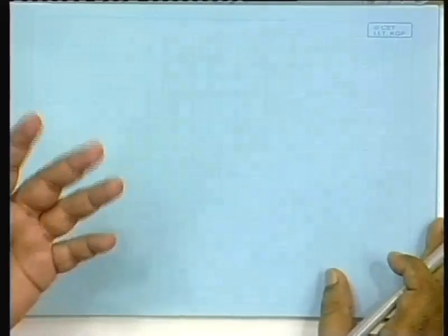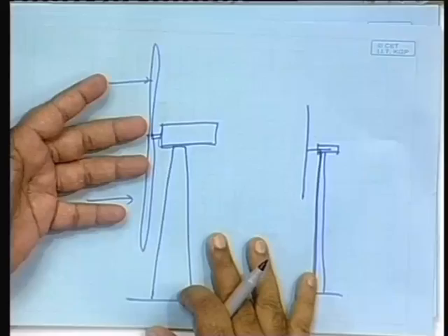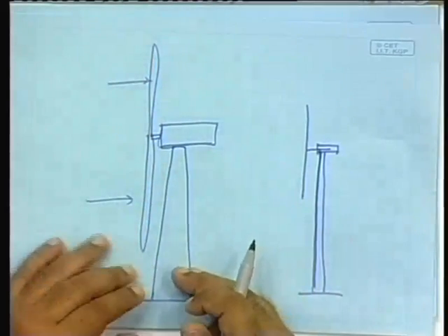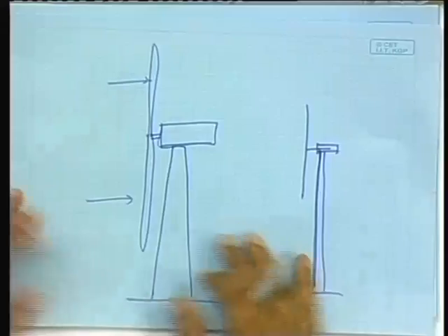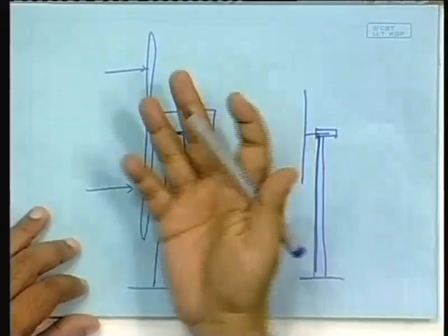You have already seen that there are constructions, vertical axis wind turbine constructions, which do not need a tower. There the whole cost in the tower is less, and therefore, they are far easier and far cheaper to construct, but they have the problem that if you have the tower that reaches higher altitudes, at higher altitudes you have got higher wind speeds, while if something is constructed close to the ground, it does not have access to the high wind speeds. But that is one advantage of having a tower. There is also the disadvantage that there is a large expenditure in the tower itself.